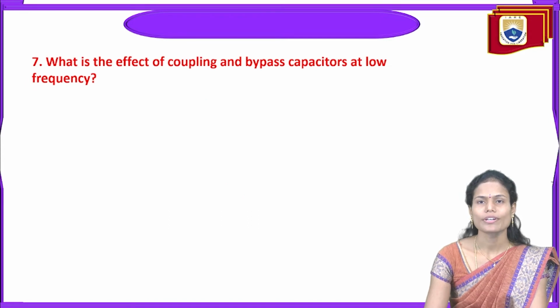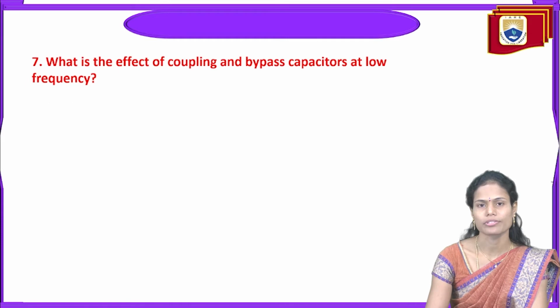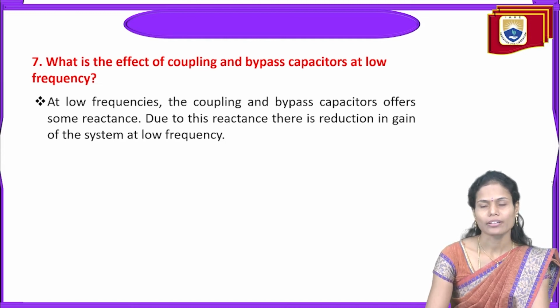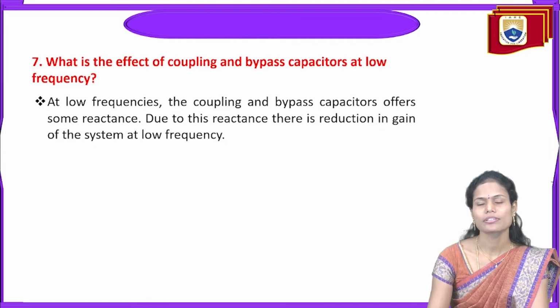And next, what is the effect of coupling and bypass capacitors at low frequency? At low frequencies, the coupling as well as bypass capacitors offer a very small amount of reactance. Due to this reactance, there is a reduction in the gain of the system at low frequency signals.